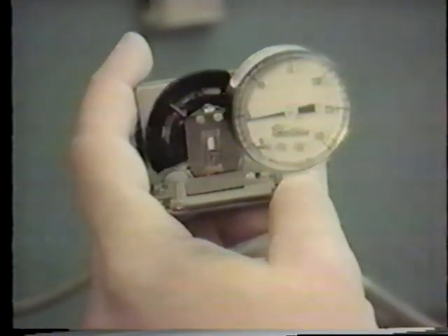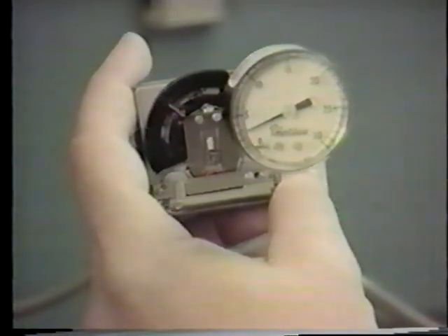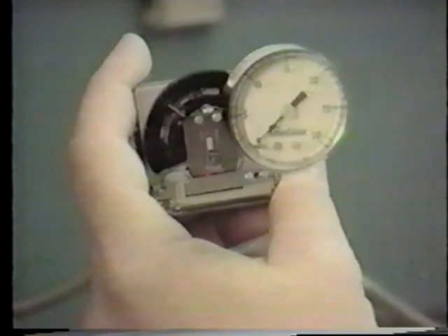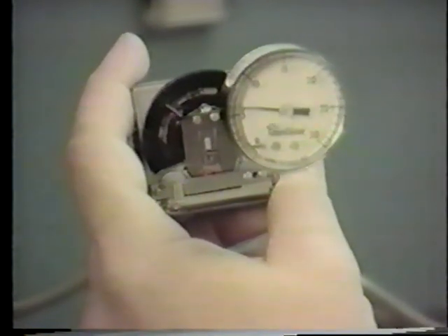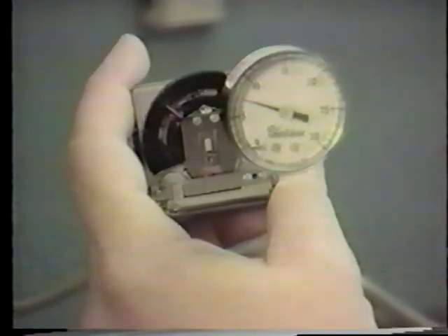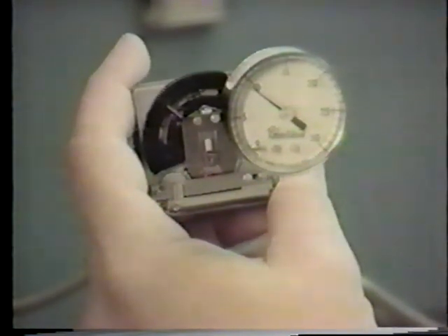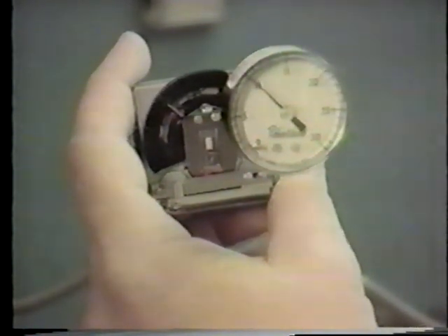As the main air pressure is raised past the switchover point, the branch line pressure should drop to 0, then return to main air pressure when the main air is lowered past the switchover point. The calibration of both day and night settings should be rechecked after any adjustment to the changeover set point.